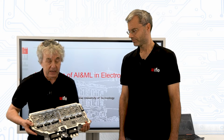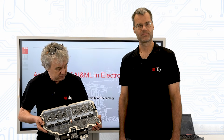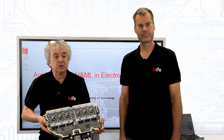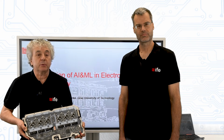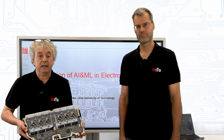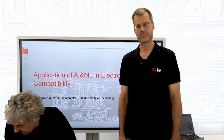Here we have a drive system from a BMW, an electrical BMW, and you see all the drives and transistors, and all the switching elements cause a lot of electromagnetic noise. The noise can disturb radio reception, the noise can disturb other functionalities like airbag in the car, and so the noise needs to be filtered very well. And filtering is done with such a filter.